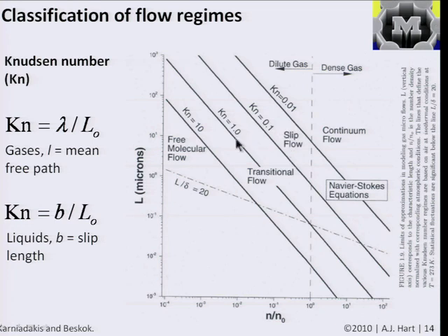And if you go down in scale or down in density, having a more rarefied gas such that the Knudsen number goes up, then you go into regimes where you really need to model the flow at a molecular level and consider the true interactions and attractions between the molecules. But in our case, we're going to operate mostly in this regime.